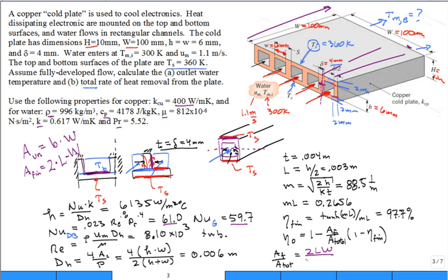You divide by BW plus 2LW. The W's cancel, and we're left with 2L divided by B plus 2L. And so that computes to a half, 0.5. So when we stick that into our equation to get the overall efficiency for the surface, it comes in even higher. It comes in at 98.9%. You could round that off to 100% and do just the same, but I'm trying to show you all the details if you want to reproduce it.